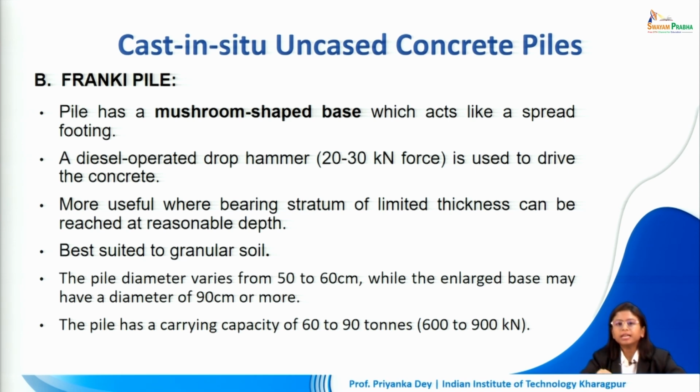The pile diameter varies from 50 to 60 centimeter, while the enlarged base may have a diameter of 90 centimeter or more. The pile has a carrying capacity of 60 to 90 tons, so 600 to 900 kilonewton.